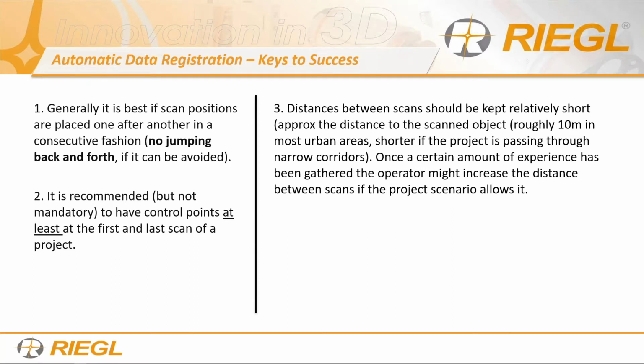Distance between each scan position is relative, right? And is really relative to the objects that you're scanning. So if you're doing a residential neighborhood where you're scanning on the sidewalk and the house is 20 feet away from you, you want to move it 20 feet because that's the object that you're trying to scan.